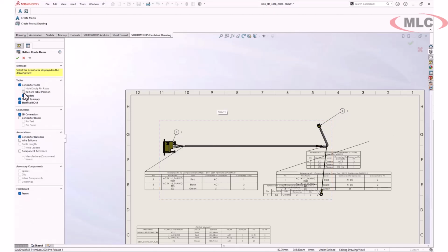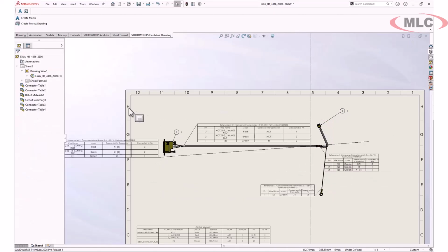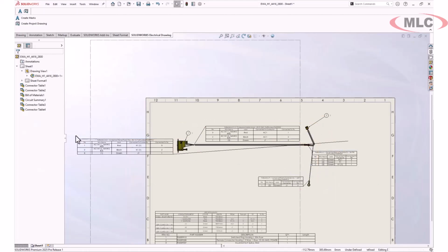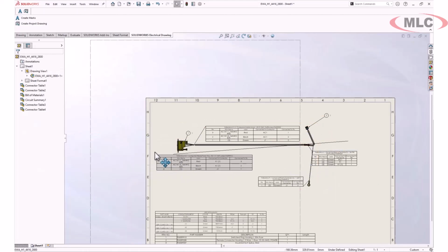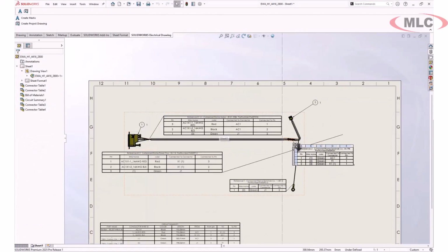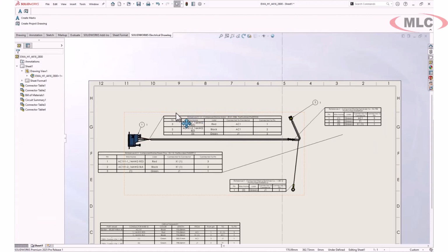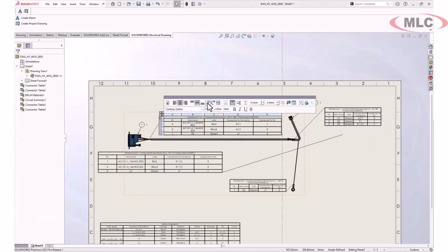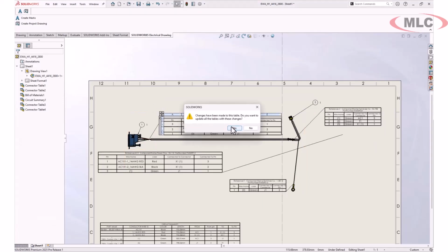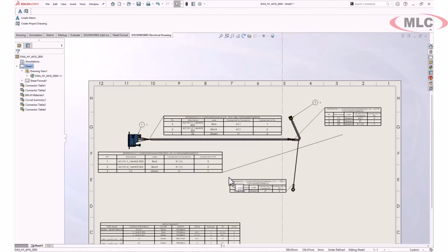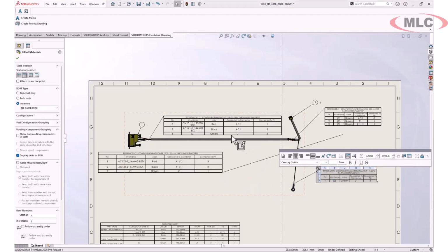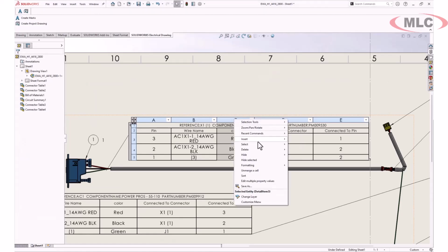Show and Hide Flattened Route Items has a new option to create an automatic leader line for each connector table. A nice visual link, especially in busy drawings. You can use these boxes to insert tables that were removed or not added. Connector balloons now display quantity similar to wire balloons. There's better logic for placement. Connector tables are placed outside the drawing view and do not overlap each other.